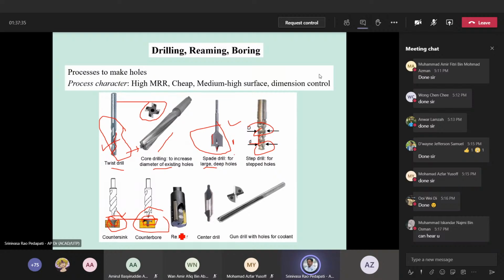And a reamer is also a special kind of tool which is also used to enlarge. It is something like you see here. This is the tool which has an insert. Insert means a detachable piece. So the insert is at the periphery. And a typical drill called a center drill is just to mark the center on the pieces. That means it only has one tip.